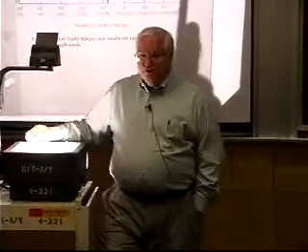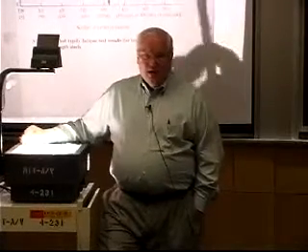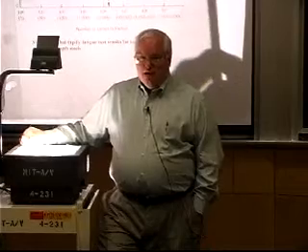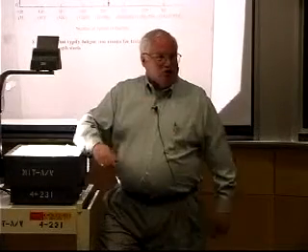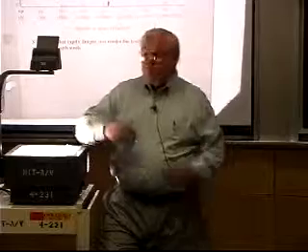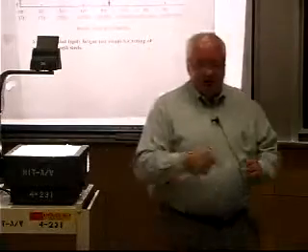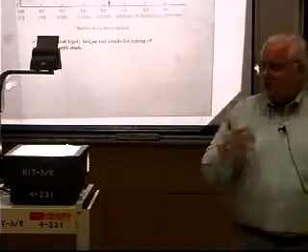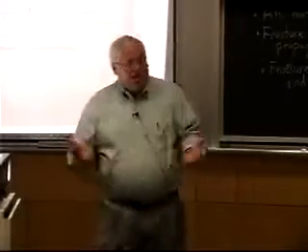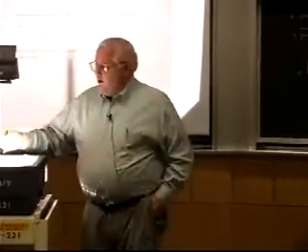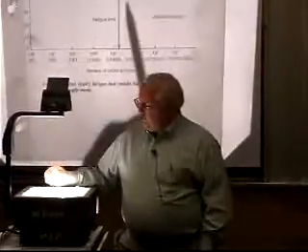There are people who've done 10 to the 8th cycles in a very few samples, and some people have done 10 to the 9th, but that's when they're putting in a special machine and vibrating at 100 hertz or even 1,000 hertz. Well, you run into problems there in your testing because you can overheat the sample just because you're putting enough mechanical work in it that it can heat up. And so now you're not doing a room temperature test anymore. So you run into limits as you go through things.